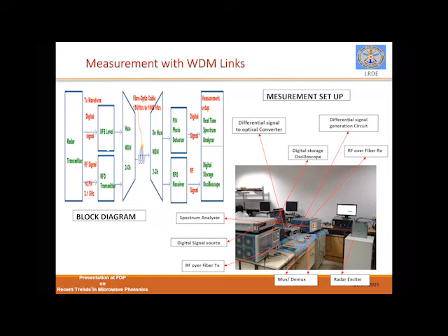In the case of the digital signal, a simple DFB laser is enough for converting to the optical domain. And here we require, depending upon the frequency, I don't know how many of you are exposed to the terms direct modulation and external modulation. You will all agree with me that when the frequency of the signal increases, because of the chirp effect we cannot use direct modulation. Then we have to go with modulators, with external modulation.